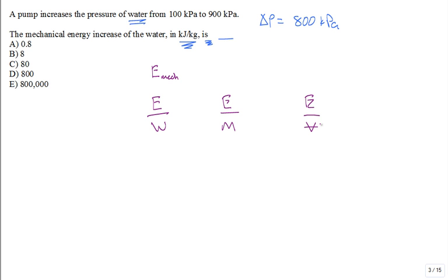That would be like talking about pressure. This one is a specific head. Maybe I'll use capital H as the energy per unit mass head. And this one is lowercase h for the head that most people would say, the head of the fluid flow, is so many meters of head.